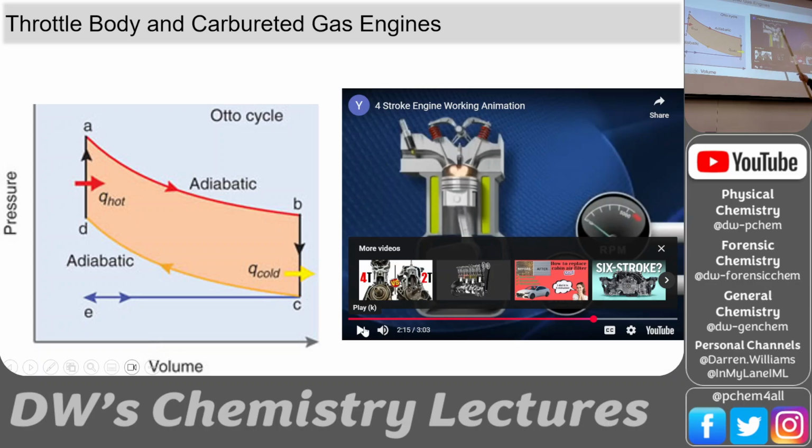If you notice, it's hard to see, but if you came up here, you'd see there's a little rod there, and on that rod are some oval-shaped objects called cams. As it spins around, it comes around like that and causes that thing to rock up and down, and that's what pushes the valves open. Yeah, so that's the camshaft on top. And when you have 2 rows of those, we have dual overhead cams, DOHC.